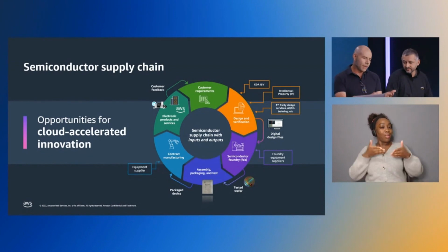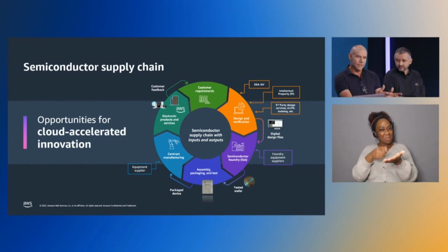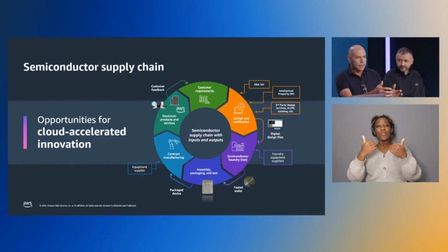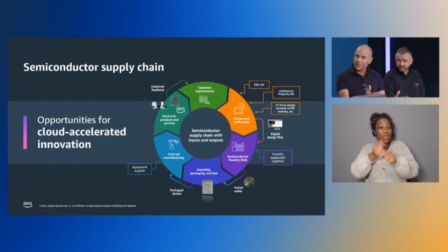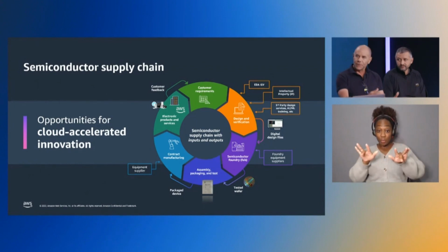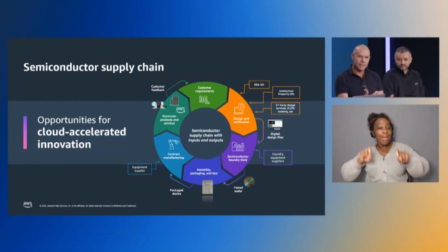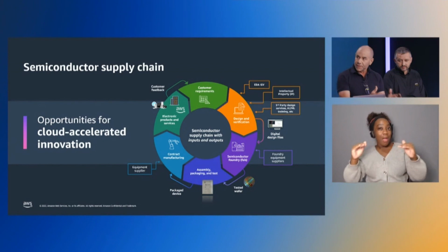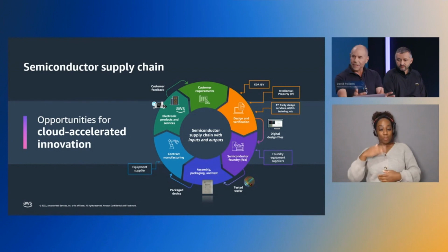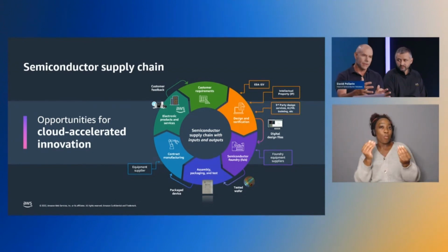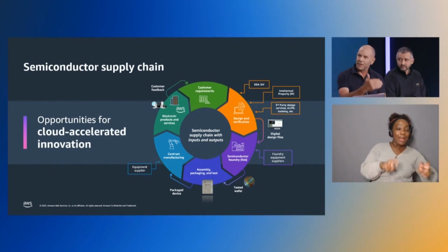But if you think about simulation at the front end, sometimes that's interactive. You've got a piece of a circuit or a digital design that you're trying to determine is functionally correct interactively. More of the compute that happens in simulation, though, is more batch-oriented, where you're running big regression tests or simulations that are system level or analog and mixed signal. And that can go for quite some time with many team members contributing different parts of the intellectual property. And then there's a back-end process of physical verification that's getting harder and harder. Timing analysis, design rule checks, those sort of pre-silicon checks for sign-off before you go to manufacturing.